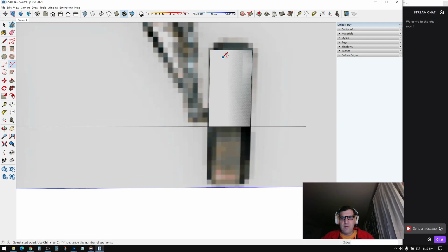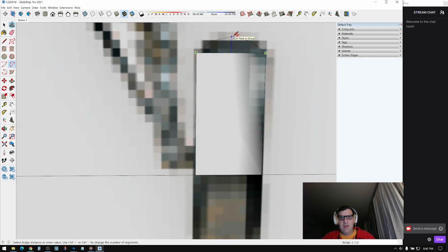Use the arc tool. How many sides does it have? 12 by default. I only need maybe 4 to make it look good. Oh, I typed 4. Okay, actually, I'll do 5. Let's see what 5 looks like. Click on the arc tool, type 5, enter. Now it should have 5 sides. Yeah, that's fine.